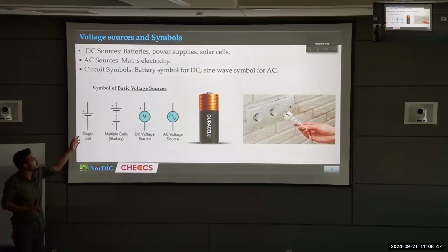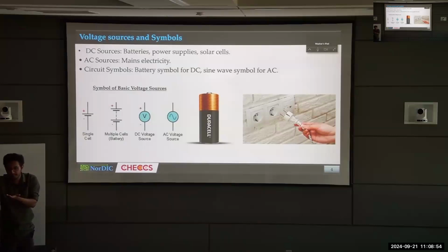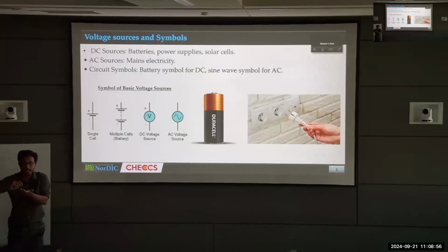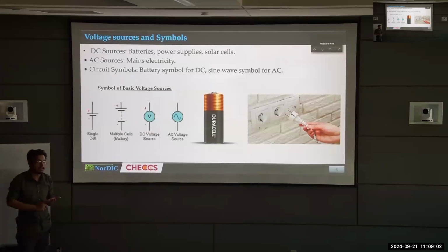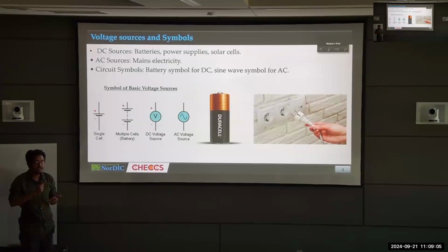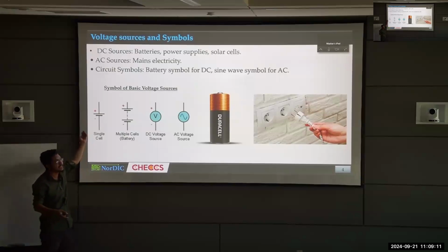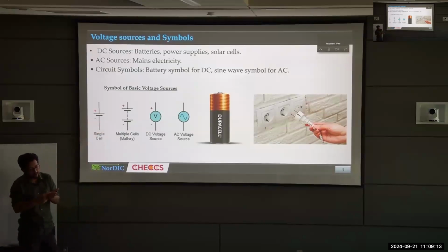Let's say you have assumed this direction of current. When you actually solve the circuit, keeping other principles as they are, you will find that at the end the current value comes out negative. Then you will know, okay, the value I have got is in the reverse direction of what I have assumed. So you will know that current is actually flowing in this direction. If you assumed it the other way, you will find the current to be positive.